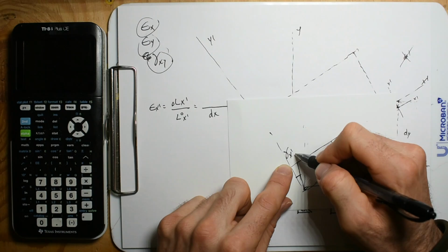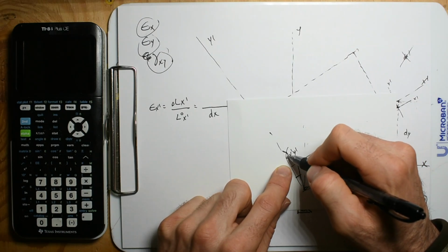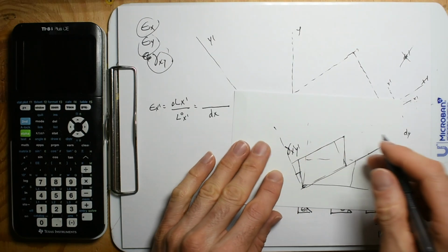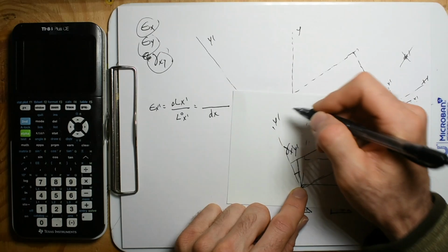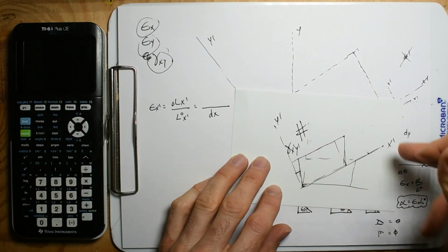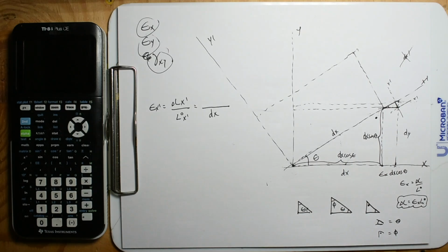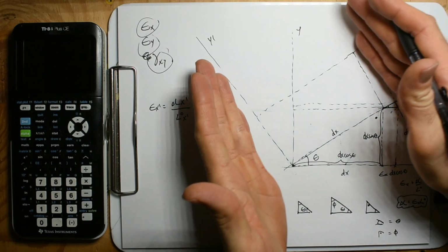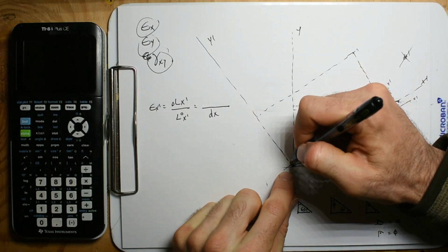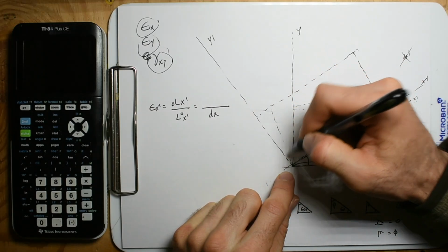So this is going to be x prime, y prime, the shear strain in this new rotated frame, and that number could be bigger. That's the whole point of doing this, that this number might be analytically bigger. And so here's our new shape. I'm really interested in this angle change.